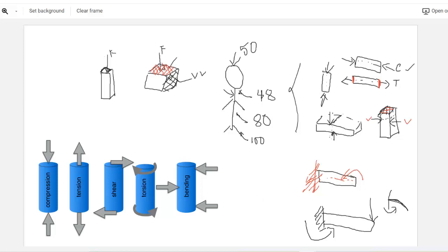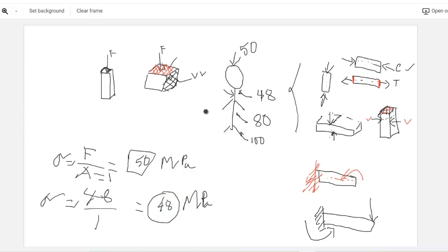So these four kinds of forces will be highly required for you. As I said, back to the main example, if the capacity of the neck is exceeded, that time the neck will fail. So now can you tell me what kind of failure it would be? Because you already understand the type of forces. Due to which forces it fails, you can name the failure on that. That would be axial failure. So now how can we say this is the axial failure? Because we can see that with respect to the neck, the force is acting vertically.